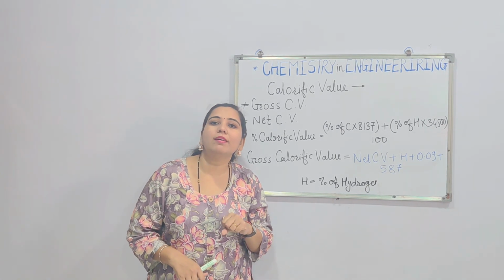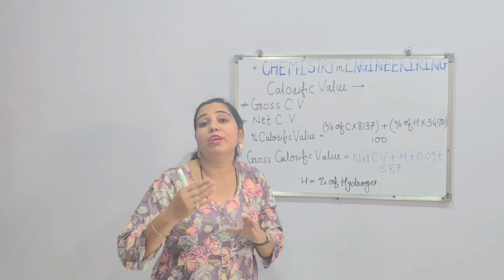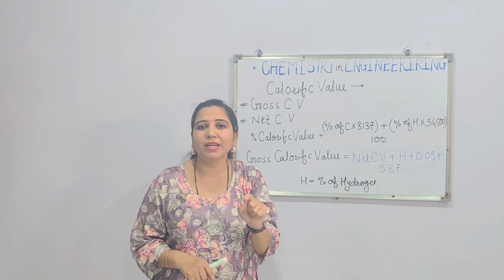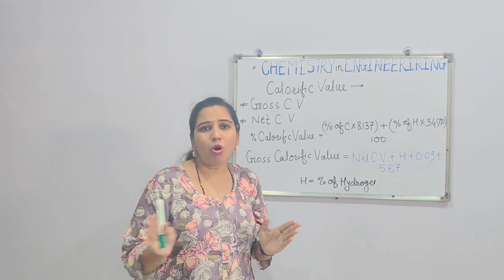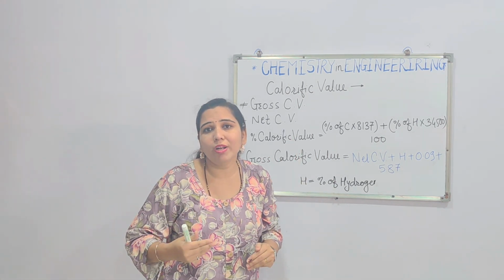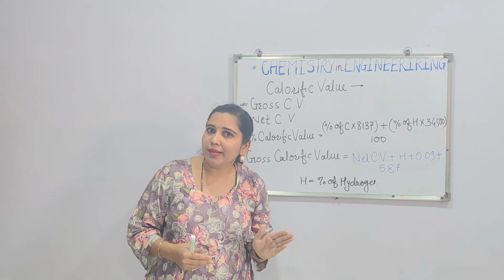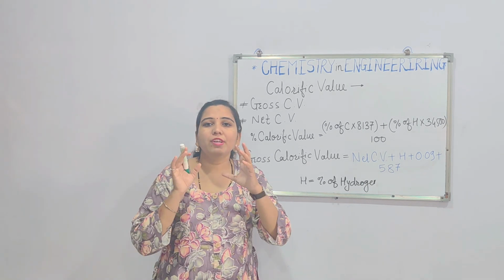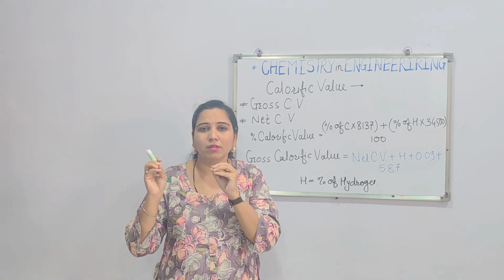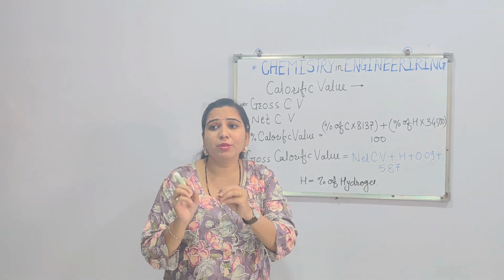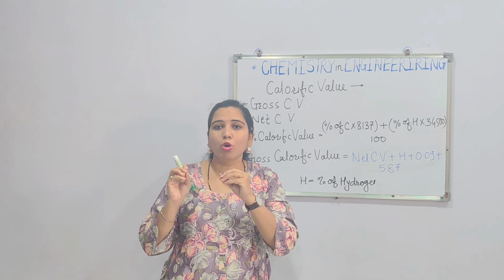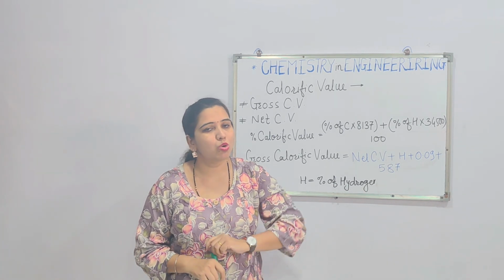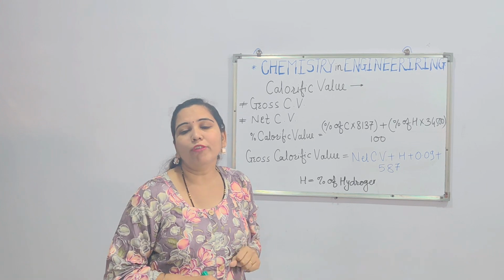Guys, on the basis of this calorific value, it depends what the quality of coal is. If a unit weight of a substance gives more energy, then the whole substance will ultimately give more energy. So a higher calorific value means good quality coal. On this basis, we can examine the coal, establish its price, its quality, or its naming according to the commercial classification. So on that basis, there is a study of calorific value.